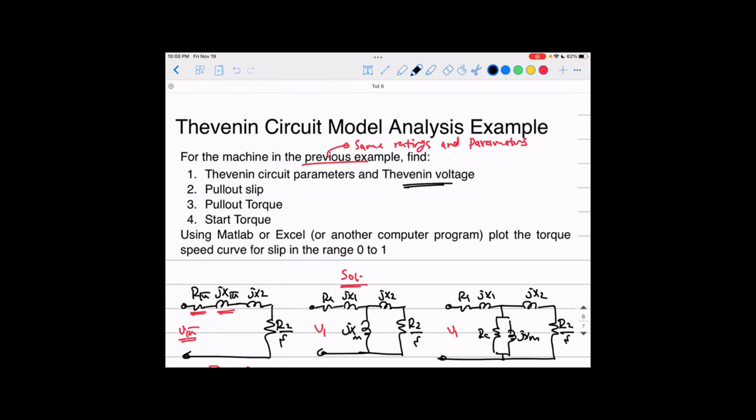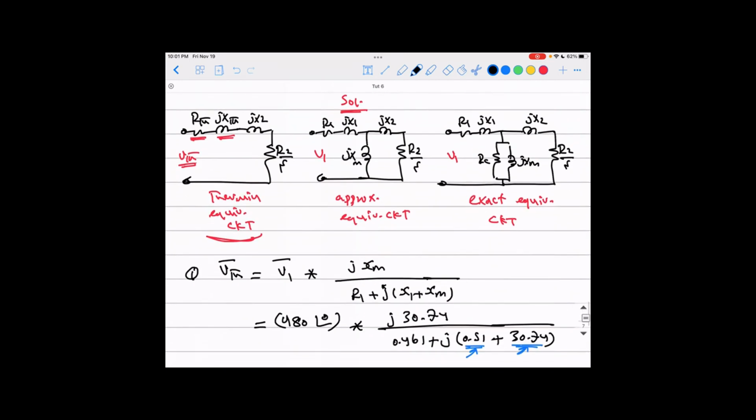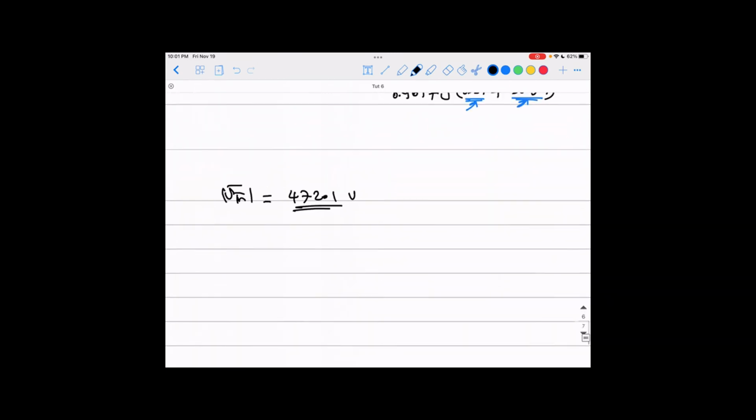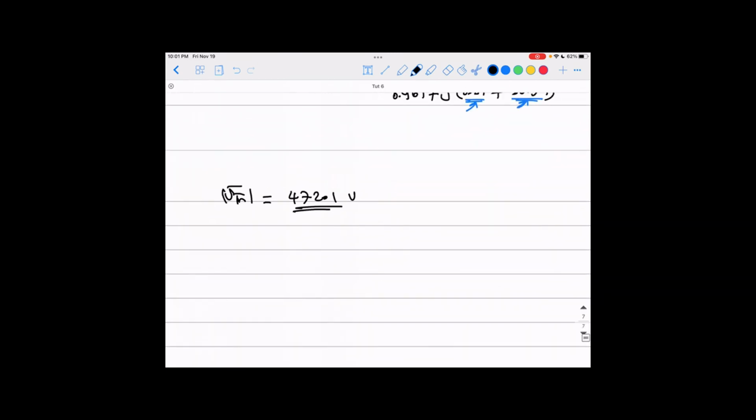Like in the previous example, when he wants you to find the line current, that means the magnitude of the current, because that is what matters most for an engineer out there. He wants to look at the magnitude because that is translated into thermal amount and into settings for the control and protection devices. So we're more concerned about the magnitude, but you can find the magnitude and angle. It's up to you. Okay.